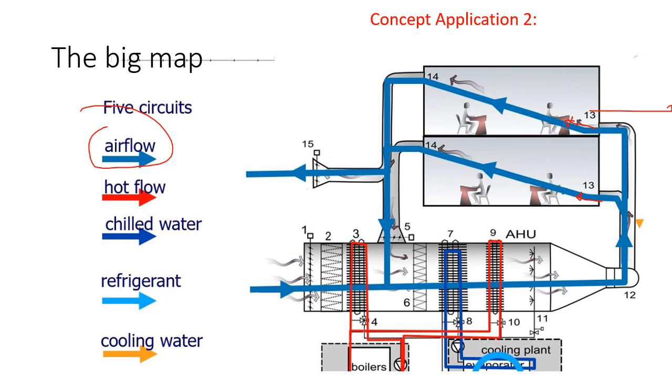In the winter scenario, the air is heated by the preheater, the cooling coil is off, and the reheater heats it again. The air, driven by the fan, comes into the room at a higher temperature, so it drops in temperature and releases heat into the room to compensate for the heat loss to the outdoor environment.